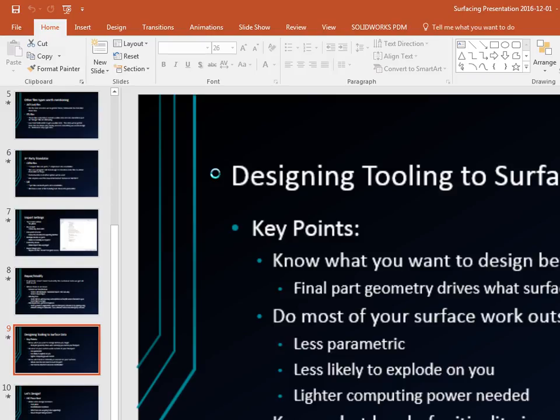So you can either untrim edges, and that will make that squared off, or you could untrim an entire body, or an entire face, sorry. The reason I prefer this is it gives a pretty clean rectangle here. It's all one continuous face. It's not making an extra face for you. It's just the cleanest. Now, it's also kind of the least likely to actually solve. So these are nice clean ones that will solve. So like here I can untrim this surface and it makes a nice rectangle for me.